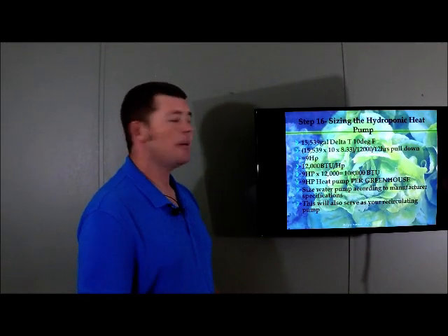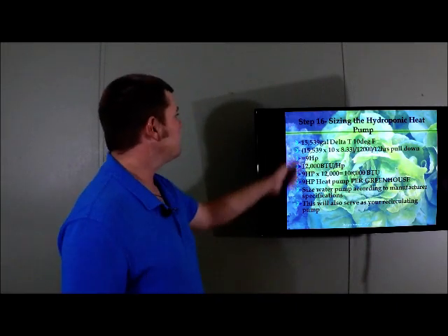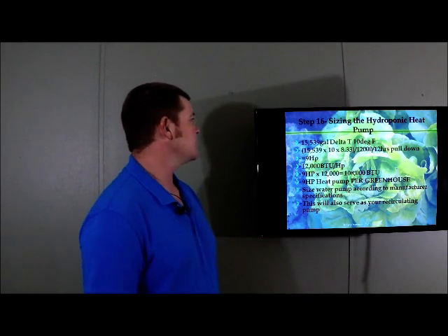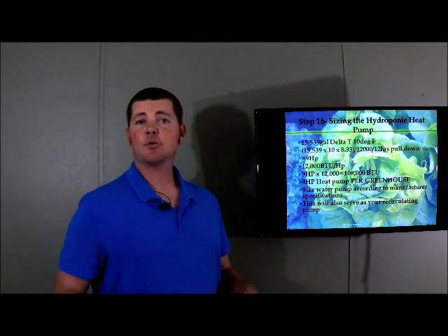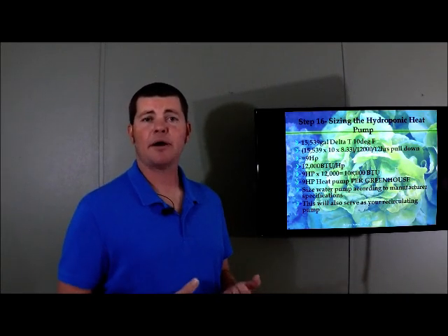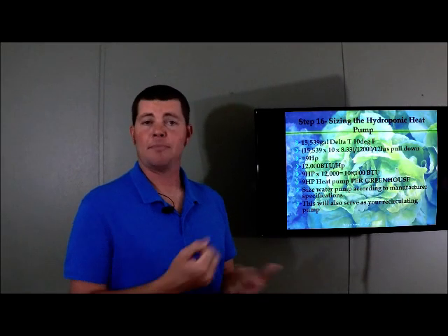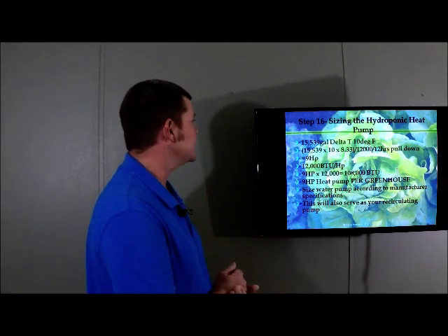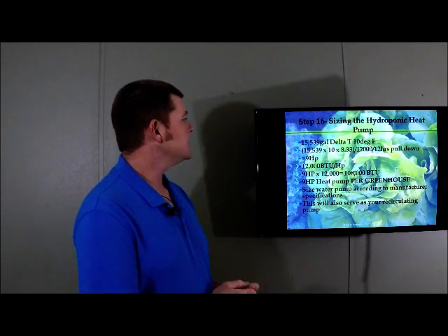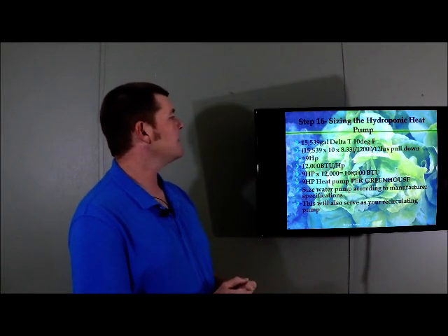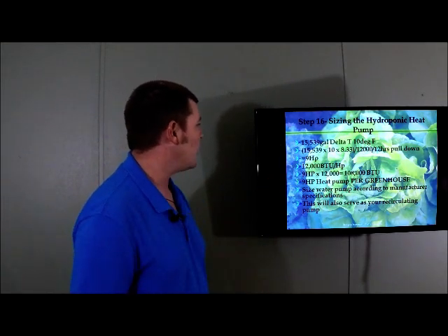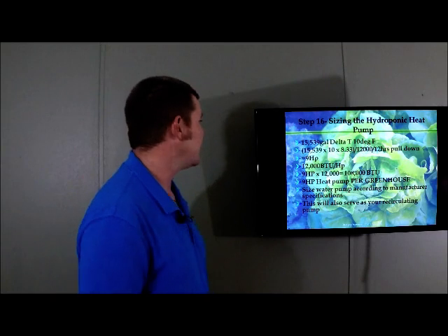So let's size the heat pump for a greenhouse. We got 15,539 gallons total, and let's say we have a delta T of 10 degrees Fahrenheit. After we use evaporative cooling and everything else we're using in the greenhouse, we still need to drop the water temperature up to 10 degrees, or maybe during the winter heat it up to 10 degrees. So we do 15,539 times 10 times 8.33, divided by 12,000, divided by 12 hours pull down, and that gives us 9 horsepower. 9 horsepower of heat pump, okay?